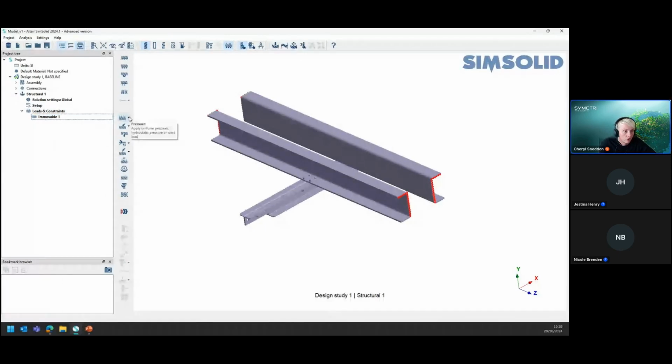So then from here, we've got the different styles. So these are the different styles of supports. So we've got slider supports, we've got hinge supports, spring supports, and any alignments. And then we've got our pressure, force displacements, gravity, inertia, remote loads and displacements, thermal loads, bearing loads, distributed mass. We've got our bolt and nut tightening, which we're going to go over. And then we've got our volume and expansion and shrinkage as well.